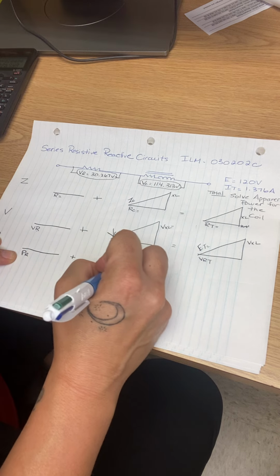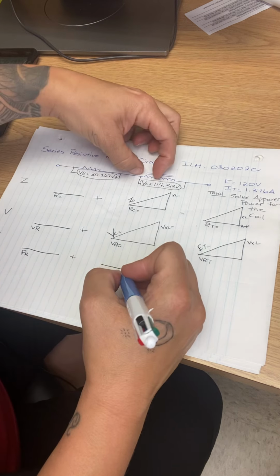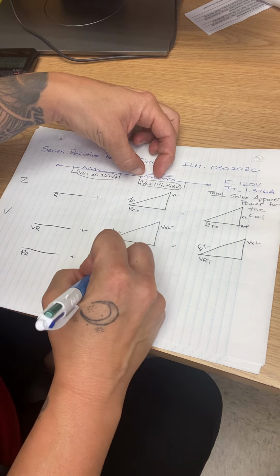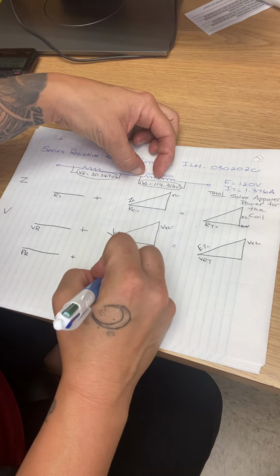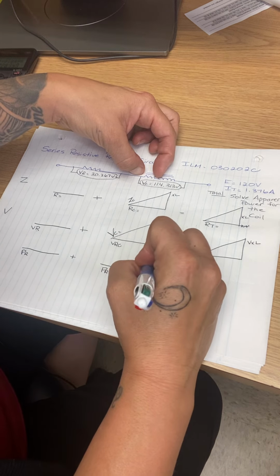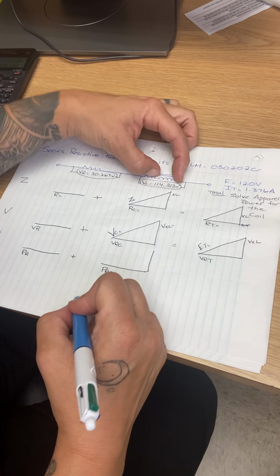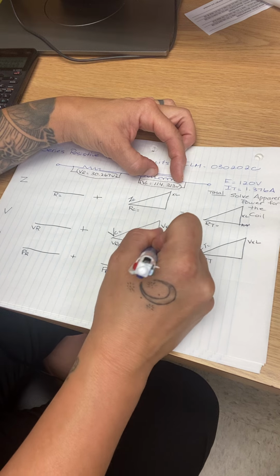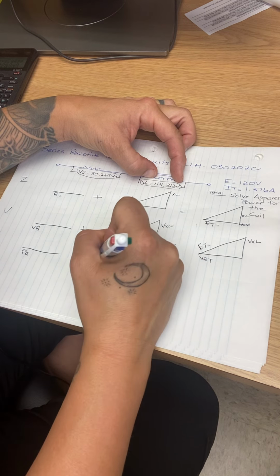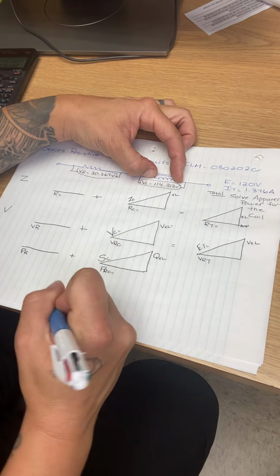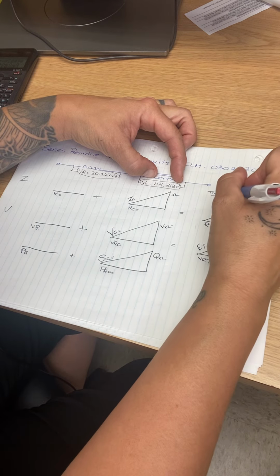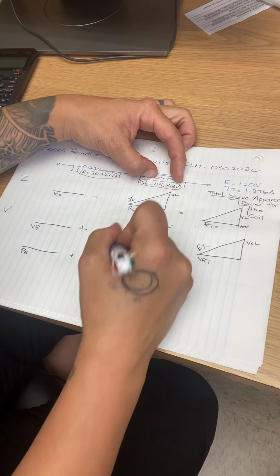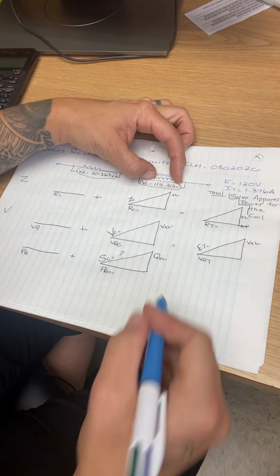Being added to my coil, the coil has an in-phase resistance, therefore it's going to dissipate true power, so PR coil. And then my power that's being dissipated from the inductive reactance portion is my QXL, and then the vectorial sum of those two sides would be known as apparent power for the coil, and ultimately that is what we are looking to solve in this particular question here.